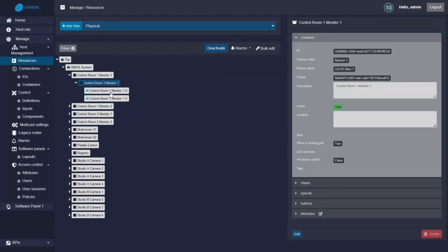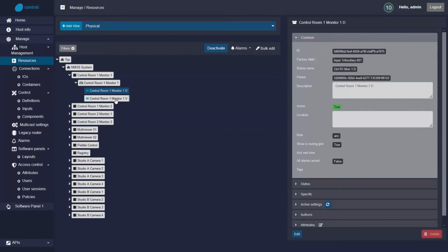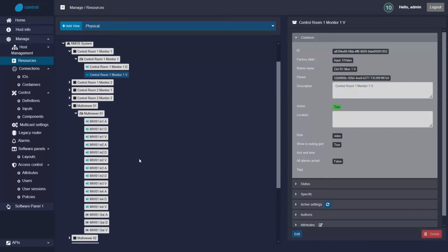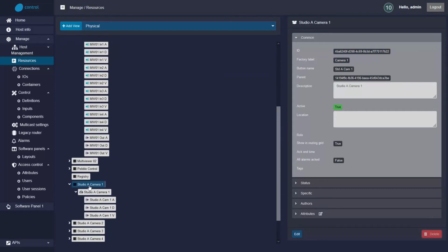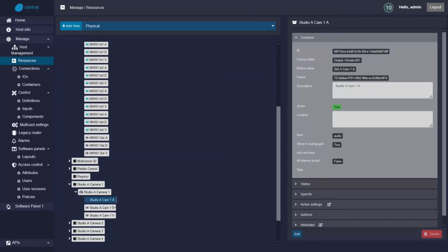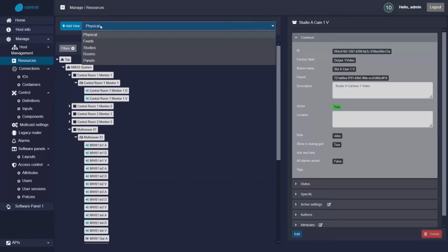The NMOS data model provides a relatively flat structure within a device, and it's sometimes not even possible to match corresponding video and audio pairs or groups. NMOS BCP-002-01 introduced some grouping mechanisms, however with some limitations, and only for devices that support that specification.